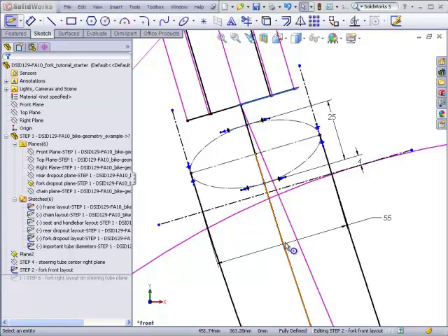As I explained earlier, this center line represents both the inside and the outside edge of the blade. The inside edge will only come up to this point of the sweep. The outside edge will come up to this point. So what I did was I just simply made sure that this was long enough so that it will accommodate both guide curves when we get to the point of making our projected curves. So I actually made it go all the way up to the top of the crown, although I probably could have ended it right at this point.